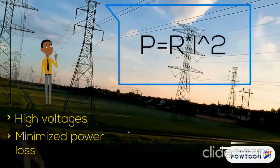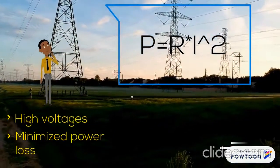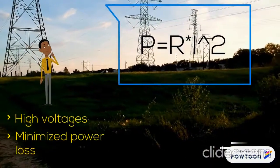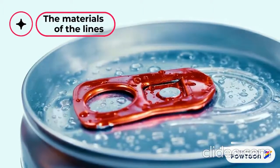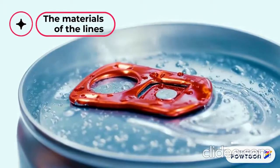As we can see, the power loss is proportional to the resistance of the line and to the square of the current intensity. In order to minimize the current intensity and thus the power loss, we can raise the voltage, maintaining the same power. These electrical highways are difficult to install and very expensive, so to make electricity transportation cheaper, big companies use aluminium for conduction.